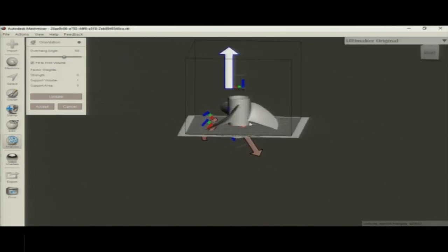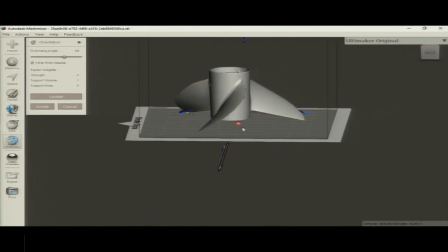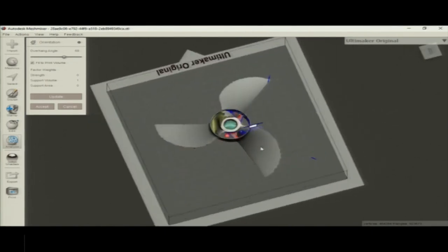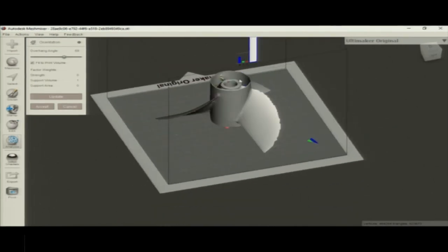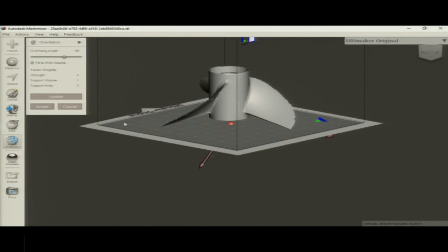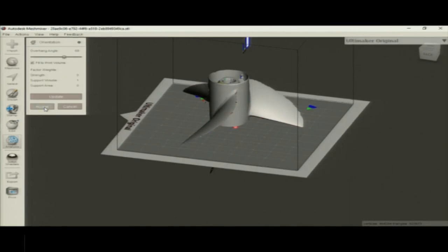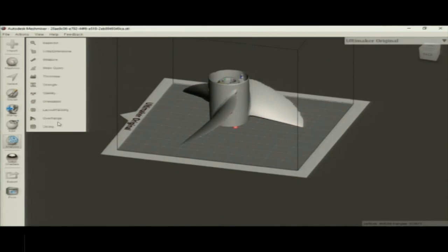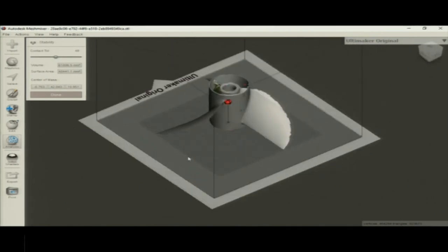So now it is selected, and while putting it back in the volume, it has adjusted this orientation again. So this is the orientation that is set by the system, fit to print volume. It is pretty symmetric in x and y directions, but if the model has unsymmetric geometries, this option will be greatly useful to have a successful print. Like for instance, the small model of animals or humans or some biomedical human ligaments or so.